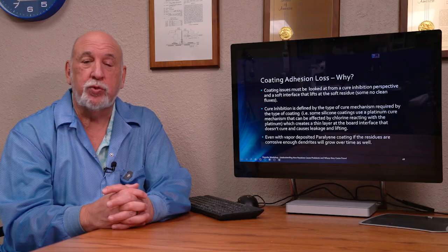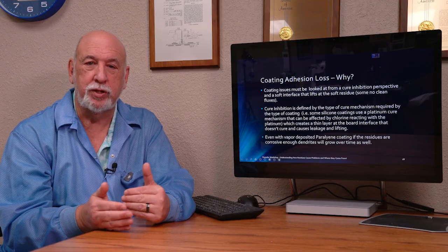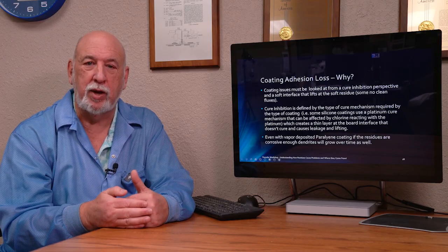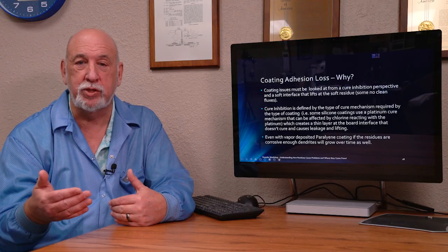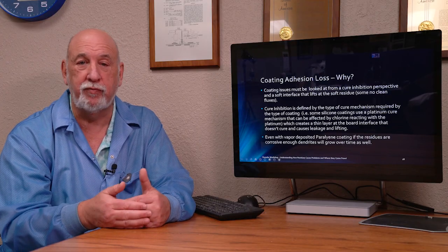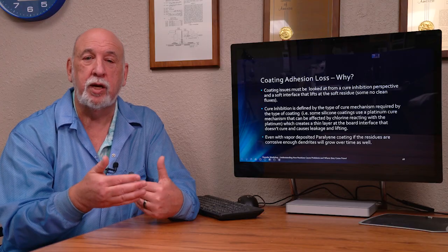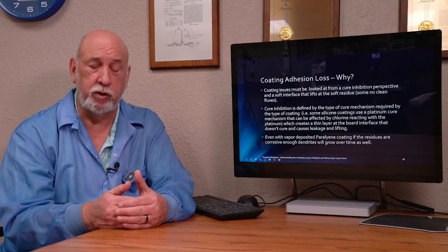So coatings, adhesion loss, one of the things that we see regularly is material absorbed into the solder mask that then outgasses later on after the cure of the material because we're not drying things out as well. So we've got moisture issues, we've got flux entrapment issues from HASL or plating chemistries trapped in the porosity of the solder mask. So we have to look at those variables.